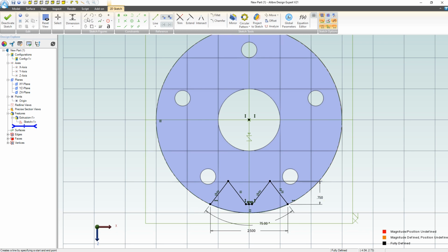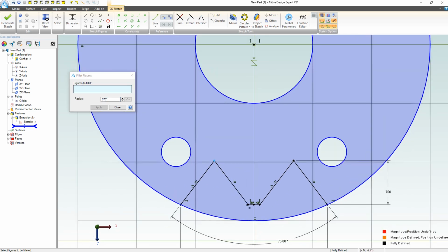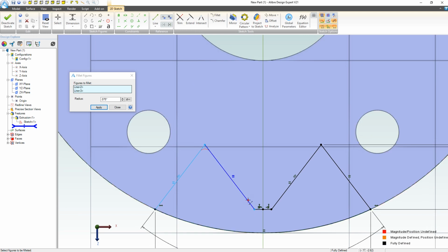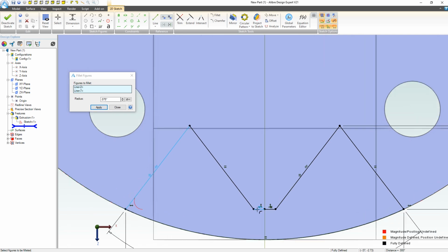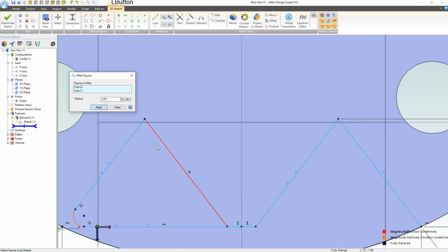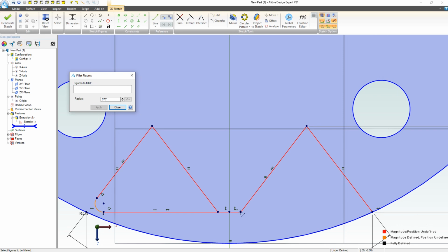We'll find out. I also want to add some sketch fillets. Looks like there. And this is the menu that comes up. I want to make that something more like 75 thou or something small. Oh, looks like I need to select the lines to create that fillet. Okay, here to here. Nice little preview. There to there to there to there. Yeah, I think my line here.